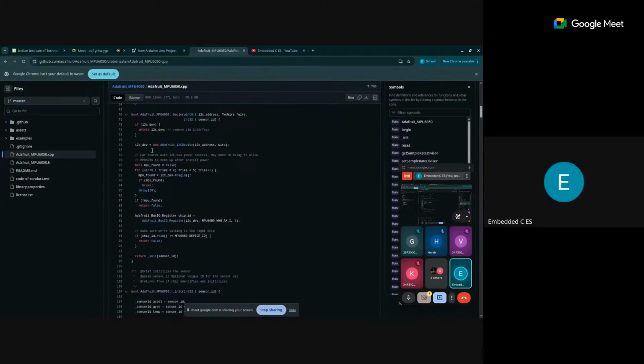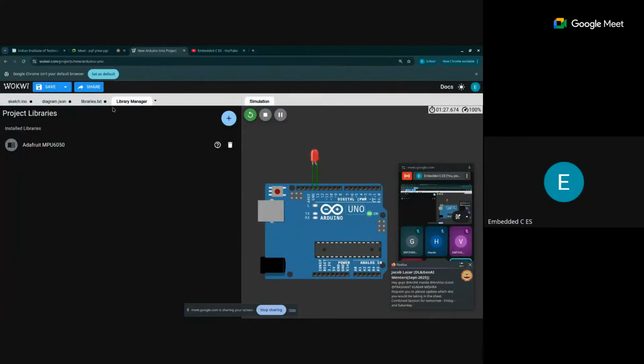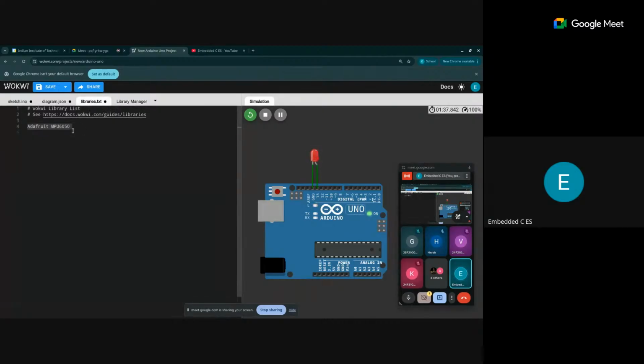If you want to design your own library yourself, you can see what kind of low level code they have used for creating this particular library. So in a Wokwi project, you have these two special files, the diagram.json describing the diagram and the libraries.txt describing the list of libraries involved. If you have used Python before, you will have something similar called the requirements.txt, which mentions the external dependencies that this particular project might want. So this libraries.txt is similar to that in Wokwi.